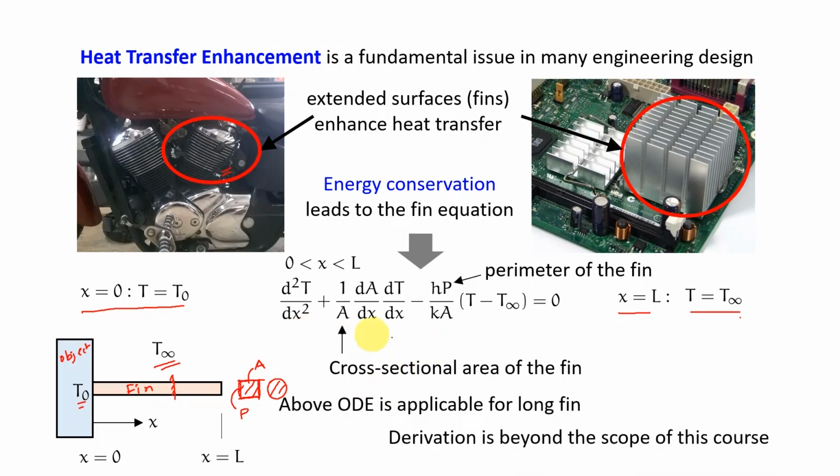So this ODE, as I said, is applicable only for a long fin because I am using T equals T infinity as the boundary condition at x equal to L. But we will not worry about that part now. We will also not worry about the derivation of this equation, which comes in a heat transfer course. We will only see how we can solve this equation.